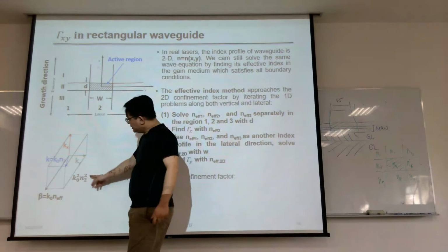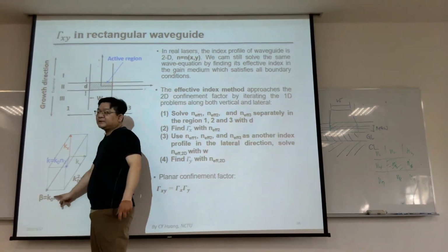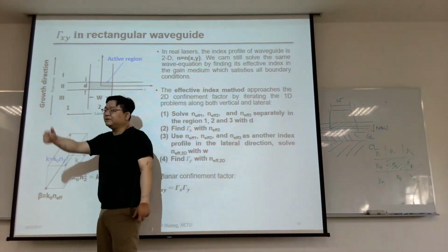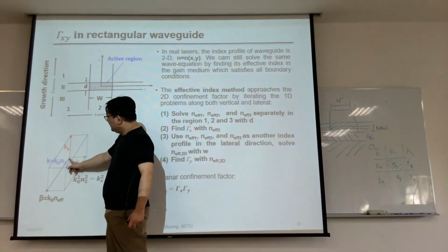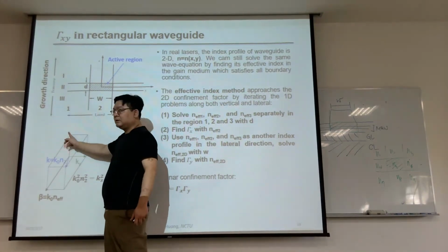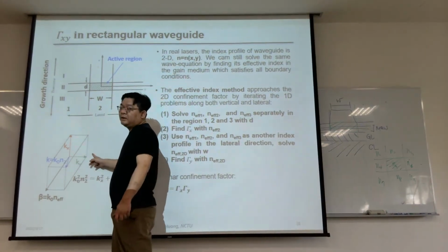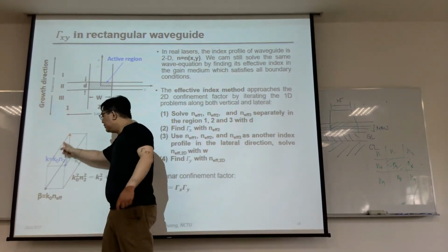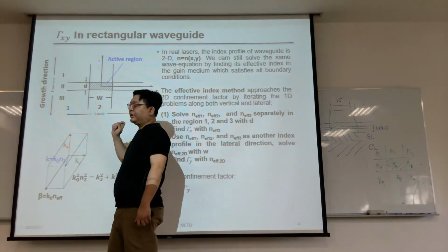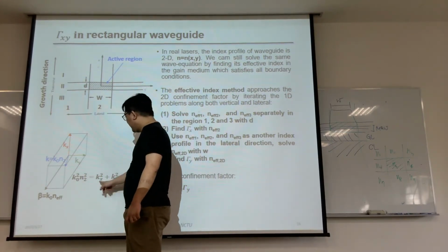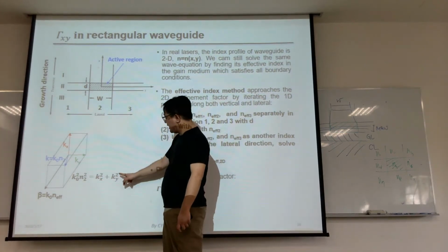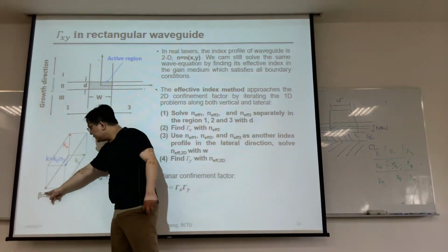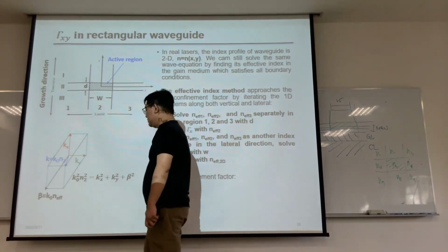You consider we also have a wave propagating outside the plane. Now this is the one going outside the plane. Then we also have the projected Kx and the projected Ky. And this K is from the diagonal of such a rectangle. So that would be Kx squared equal to Ky squared plus beta squared. And beta is K0 times N_eff.